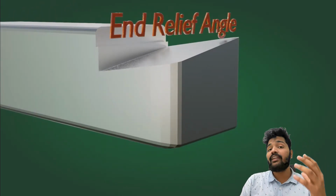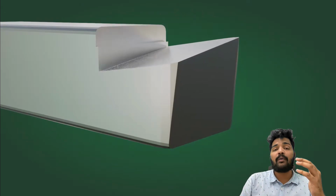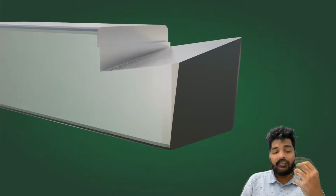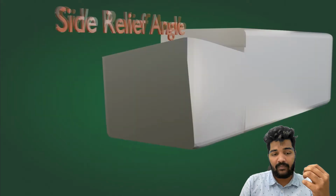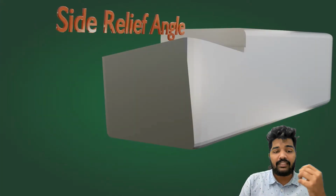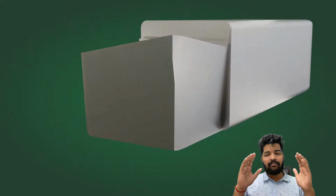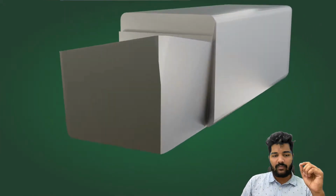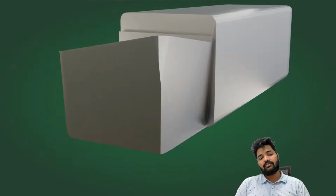Third, we have the end relief angle. Now this angle is between the end flank and a line perpendicular to the shank. Now this angle helps to reduce rubbing and ensures smooth cutting. Fourth, we have the side relief angle. Now this is the angle between the side flank and the line perpendicular to the shank. It helps in preventing friction and rubbing during the cutting process.